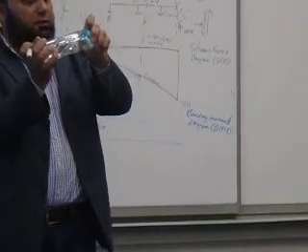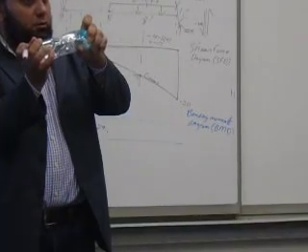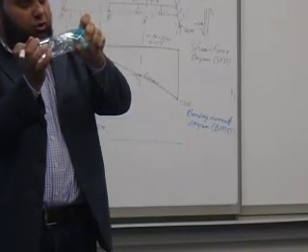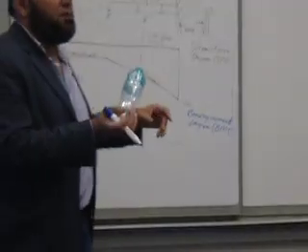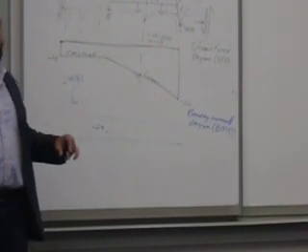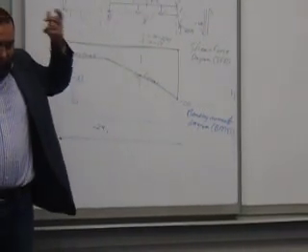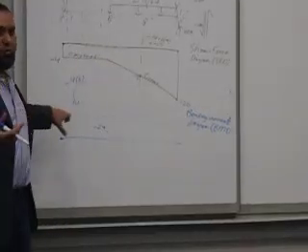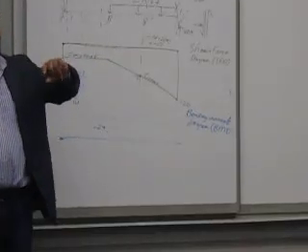The upper part is under tension or compression? Tension. The lower part is under compression. Right? This is exactly what a negative bending moment means: that the upper part is under tension, the lower part is under compression. We intentionally draw the bending moment this way to show the tail of the arrow.